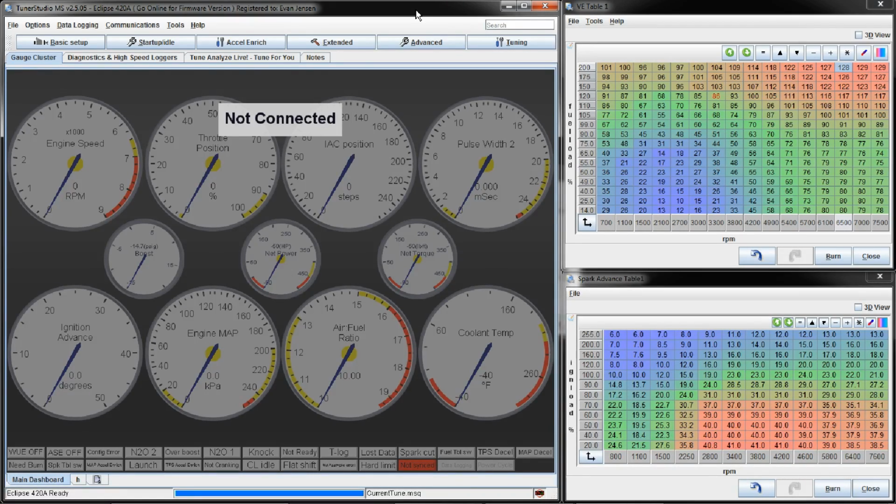and so you lose a lot of that fine resolution down low that you really need to keep a good idle. So if it's a race car and you don't care much about idle, then 1000 for sure. But that's sort of the point of going with these kind of middle of the road. You calculate what you need and use that so that you get maximum resolution over the area that you want to use.